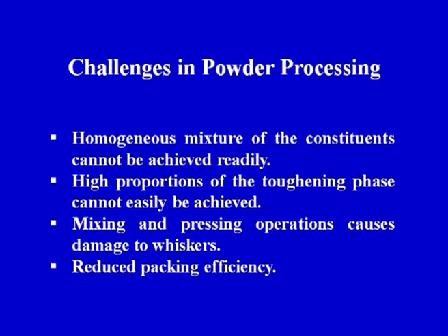The next challenge is that hydrostatic tensile stress may be developed due to the difference in the coefficients of thermal expansion of the reinforcement and the matrix. We have already seen, in the very first slide of today's lecture, that there is a difference in the properties of the reinforcement and the matrix, and this difference may lead to certain stresses developed during the processing.